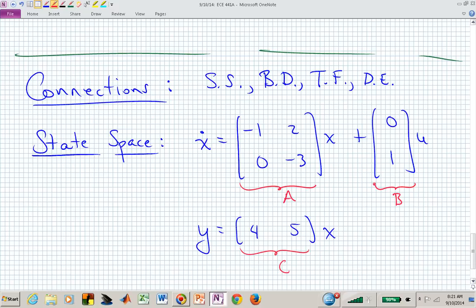This is a continuous time system, which means that we want the eigenvalues to be in the left half plane to be stable. If we converted this into the frequency domain, we would have poles at -1 and -3 in our transfer function. And those are well placed in the S domain. They have negative real parts. And they would then represent, without doing any kind of control, in the open loop system, modes that look like e to the -t and e to the -3t. And those are well behaved. If you kick it, it naturally wants to move with those modes. They really don't shake, they just decay, don't they? Those are exponential decays, e to the -t and e to the -3t. Which of those is the slowest mode?